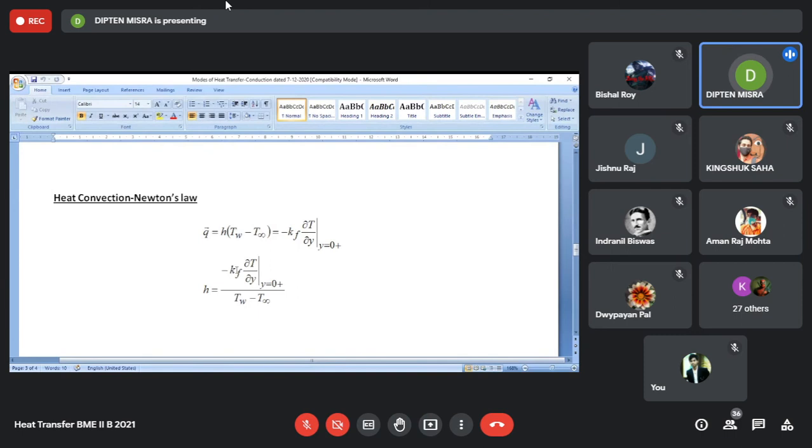For that, what we require to know is the temperature gradient. The conductivity of the fluid can be found through experimental means. It may also be available in some handbook. It is a standard material. But to find the temperature gradient again involves a rigorous exercise. This we can do theoretically, and this we can do experimentally. This we will discuss in our next class.